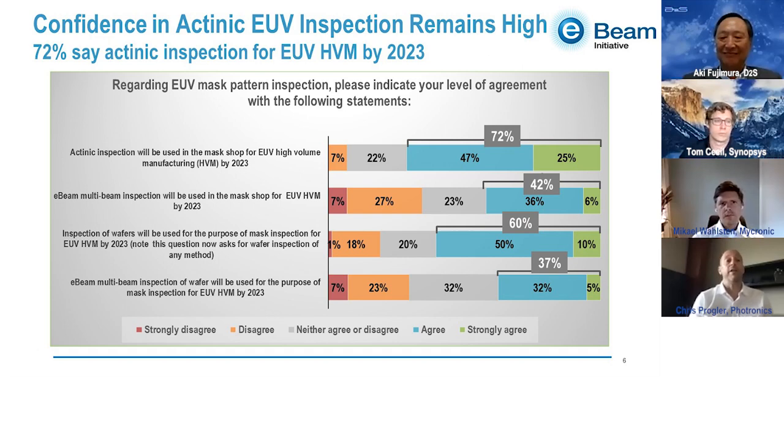Particularly with ILT, some of the things we touched on earlier, everybody's very focused on how you inspect those. But the SEM metrology on those sorts of structures, if we really want to understand what's going on, the 2D shapes, contouring features, all that stuff, the situation with CD SEMs in mask making is really inadequate. So I wouldn't mind seeing that effort push more towards measurement as opposed to defect inspection on the SEM side of things. I think that would be a little more valuable.